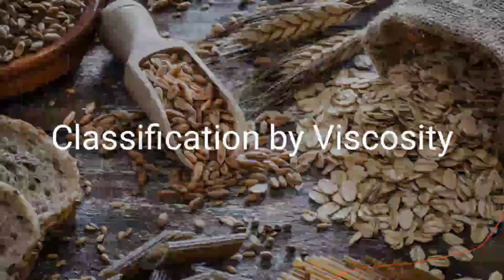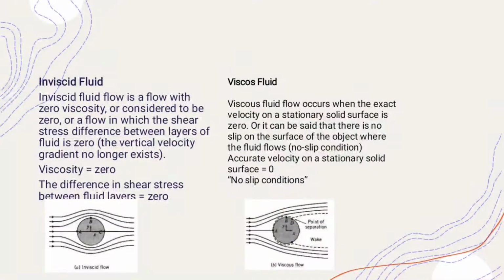Classification by viscosity. Inviscid fluid. Inviscid fluid flow is a flow with zero viscosity, or considered to be zero, or a flow in which the shear stress difference between layers of fluid is zero, meaning the vertical velocity gradient no longer exists. Viscosity equals zero. The difference in shear stress between fluid layers equals zero, as shown in the picture below.